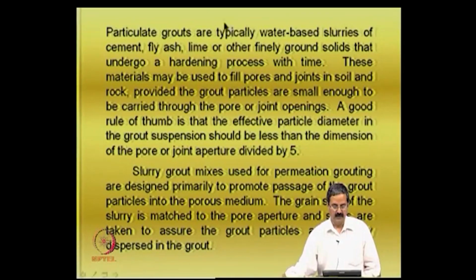In fact, people use many types of particulate grouts. As I was trying to say, the particle size is very important, and it can be cement, fly ash, lime or any other material, and they have a hardening process which is a function of time. Hardening is like it sets for some time, then the strength increases if you wait.